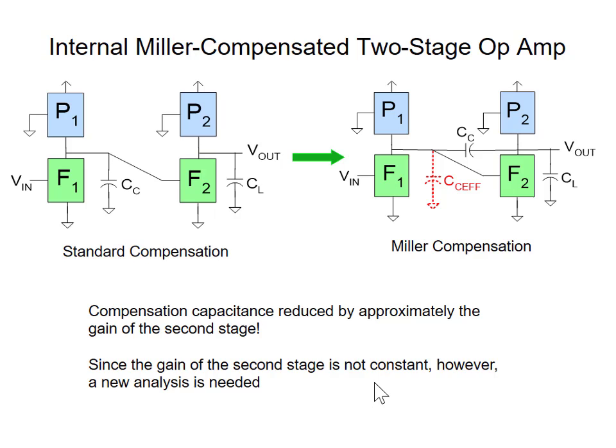So why don't we just take this capacitor here? This is a big negative gain, and that will make an input capacitance look much bigger than this capacitor here. Make sense? And then we'll put an additional capacitor on the output node, but if C sub C is small, it won't affect the overall load capacitance very much at all.